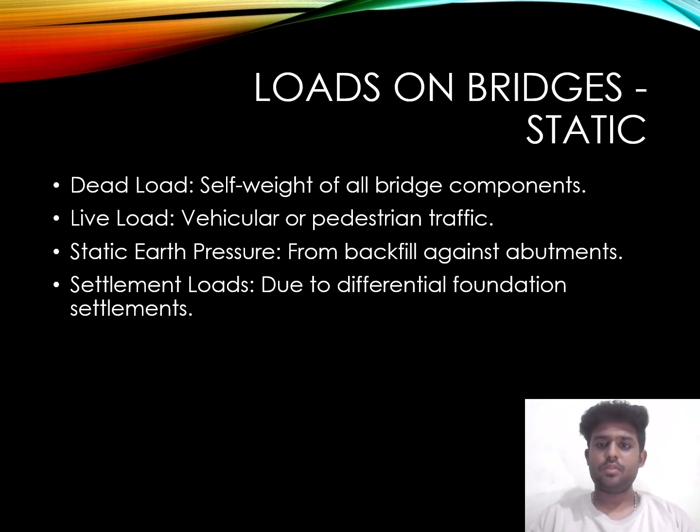Loads on bridge. Static. Dead load, self weight of all bridge components. Live load, vehicular or pedestrian traffic. Static earth pressure from backfill against abutment. Settlement loads due to differential foundation settlements.